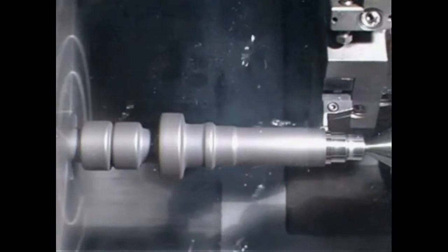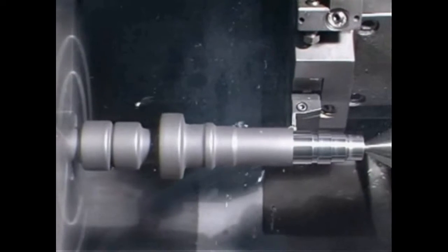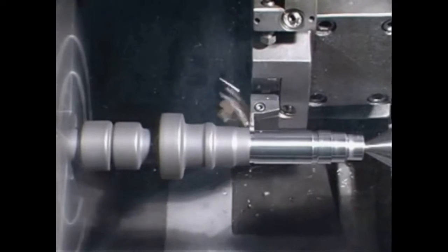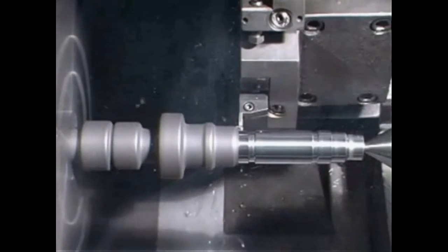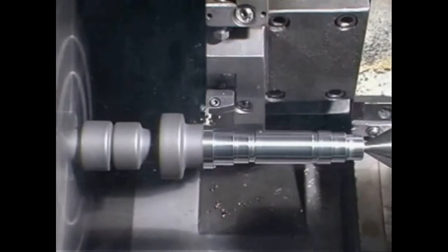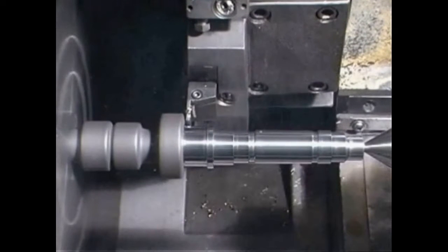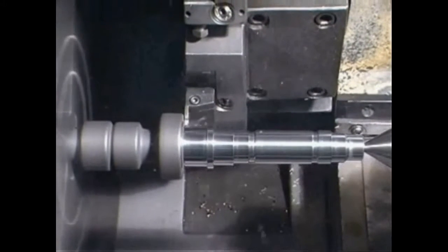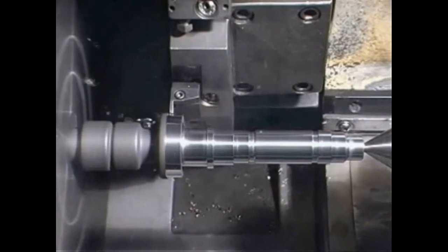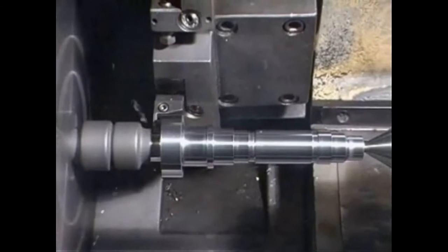This part has turning and grooving operations, and you will notice that a grooving tool is doing both turning and grooving. Grooving tools nowadays can also do turning, and CNC lathes are capable of tool paths that enable this to be done. This operation, called turn grooving, is done sometimes to reduce the tool cost and tool change time. On the vast majority of parts, the turning is done with a turning tool and grooving with a grooving tool, just like on a manual lathe.